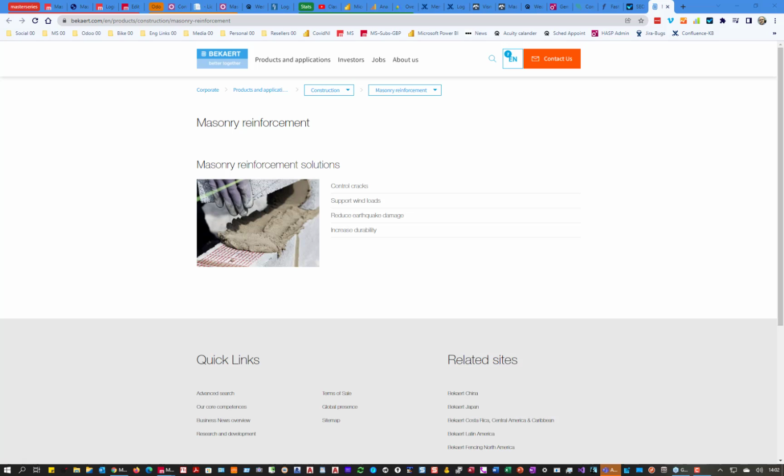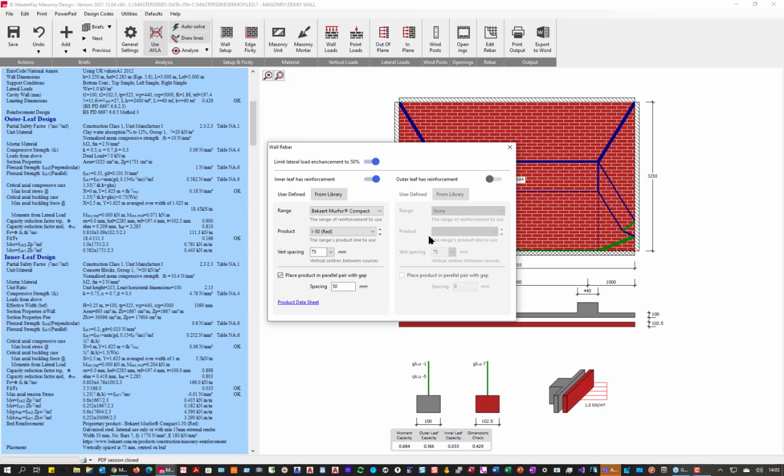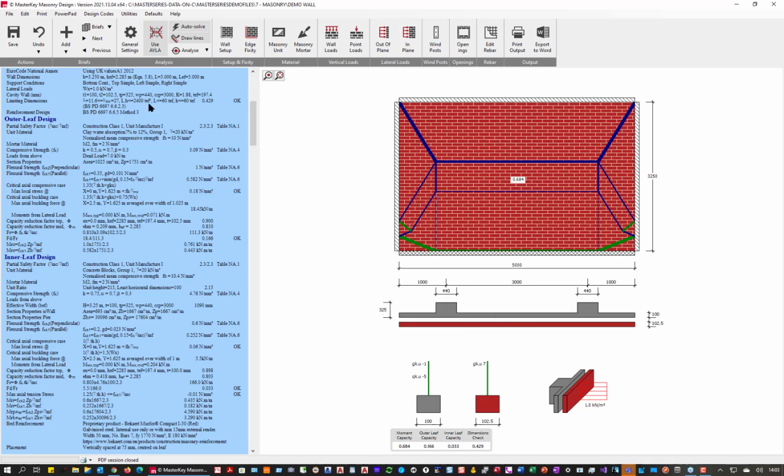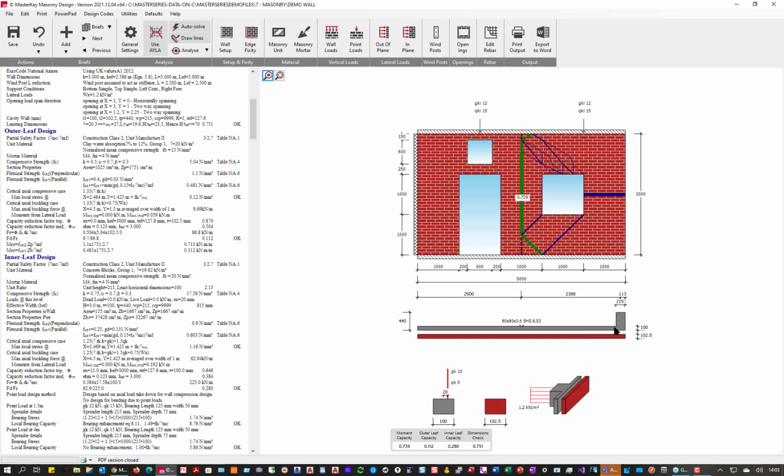Can you model a restraint to represent a return wall instead of a wind post? Well, return walls, the codes of practice tell you that if a return wall goes back so many thicknesses, then it's simply supported or continuous. Those are just basic rules in the code. But as you will remember from my first example, we did do a thick return in this case, as a pier instead of a wind post, because it did not have any other support.